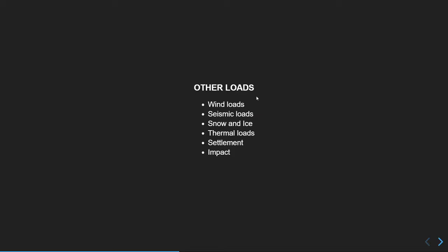Okay. So dead loads. If I have a block of concrete on my structure, that block of concrete is going to be exerting a dead load force, and we can work that force out by checking its volume and comparing that volume with its density. Volume times density will give you its mass, and that will then tell us how many kilonewtons it will be exerting, and so on and so forth. And we can say if it's a point load, if it's a line load, if it's a pressure.